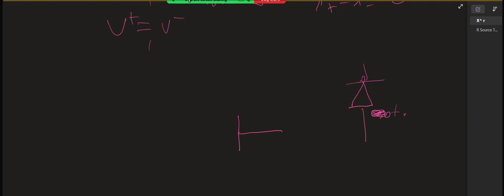Anode is at 0.5 and the cathode is at 0. Okay, so this one I hadn't gone over yet. So this is false, but the reason it's false is not because the signs are wrong. It's because you need to have 0.7 to be forward biased. So this side needs to be 0.7 higher than the other side. So this is not yet forward biased. So that's why that one is correct.